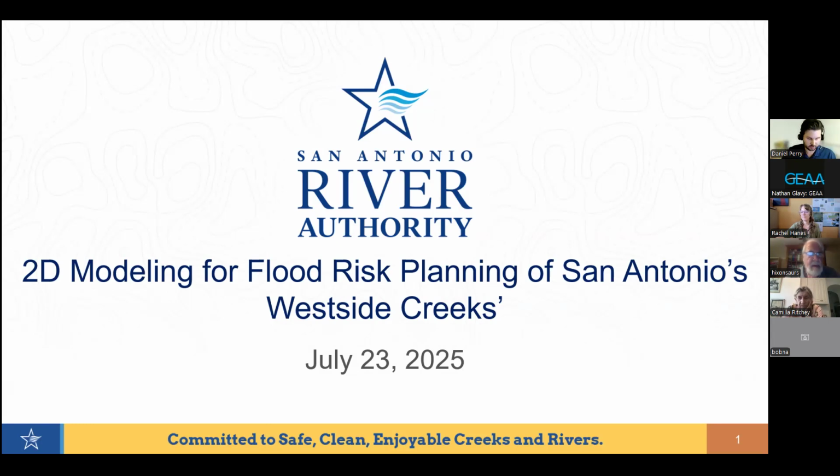Awesome. Thank you, Rachel. Like Rachel said, my name is Daniel Perry, and I work for the San Antonio River Authority, and I'm an engineer at the River Authority, mostly focusing on water resources and floodplain development. In this presentation, I'll try to go a little bit into FEMA's floodplain development and the reasoning behind it, and their role in floodplain development, and then get into our 2D modeling purposes of the 2D model and what we developed and show some of the results.